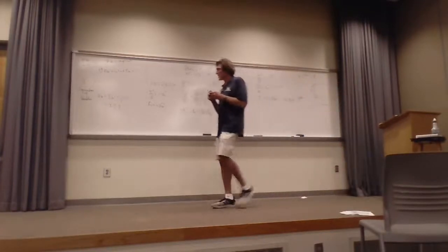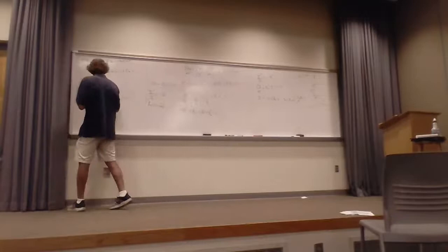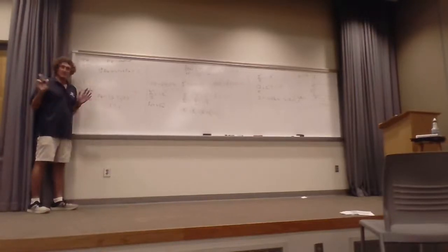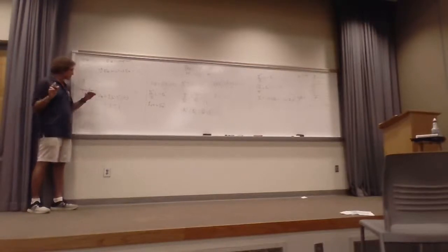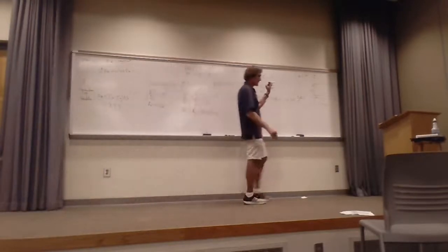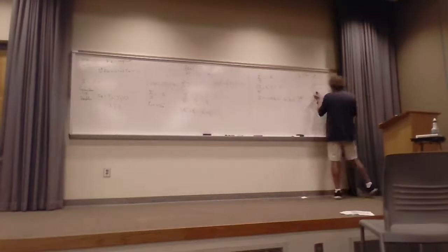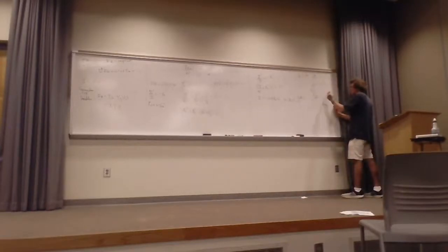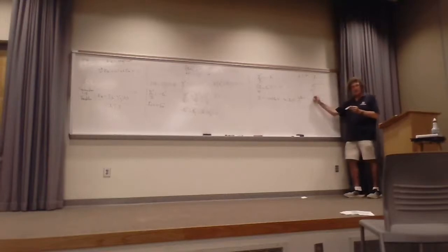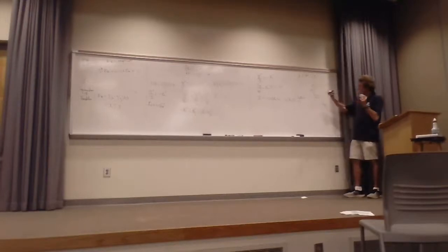Remember I said that EZ was multiplied by this times this times this, right? Now, at the boundaries, this has to be 0. Do y'all agree with me? EZ is in the direction of propagation, right? So it's going down the guide, and we know anything that hits these edges, the tangent component is 0. So EZ has to be 0 here, right? If you think of EZ, it's actually pointing in, right?